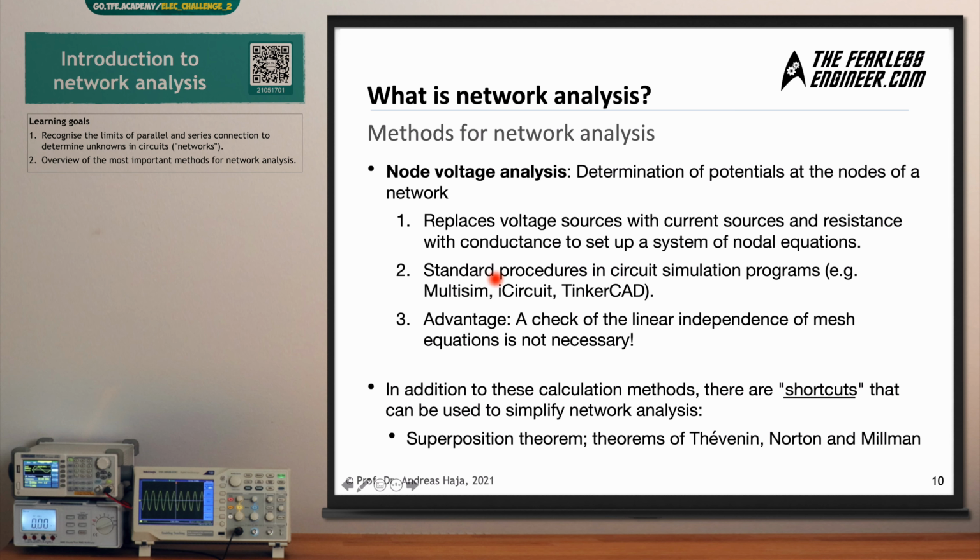For example, Multisim or iCircuit or Tinkercad. These are some of the programs which I have talked about before, which you can use for very easy simulation of networks. And the advantage here is that checking for linear dependencies between all these equations is not necessary. With the other methods, sometimes if you have multiple equations, you need to carefully check which to use. Let's say you have 4 equations and you have to decide which one to use.